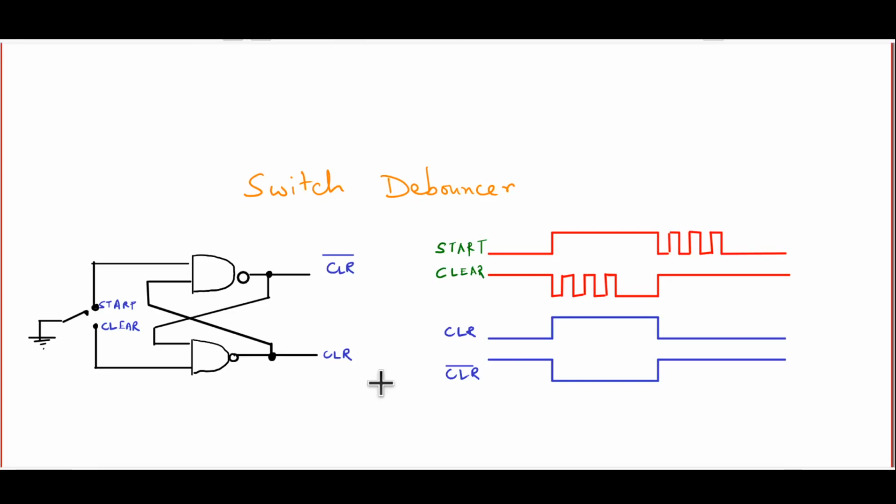a computer. The reason behind that is simple. A digital computer usually consists of thousands of such flip-flops, and it is important that they act in a coordinated manner. And in order to coordinate the behavior of these flip-flops, you essentially use a square wave input. This is called the clock signal. What this signal does is that it prevents the flip-flops from changing the output state at random times, and allows them to change the output only at certain fixed intervals of time so that these changes occur together.